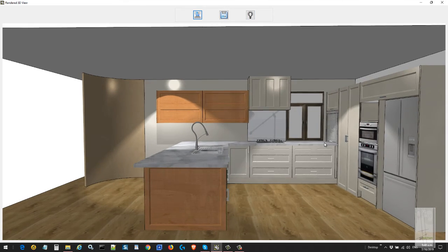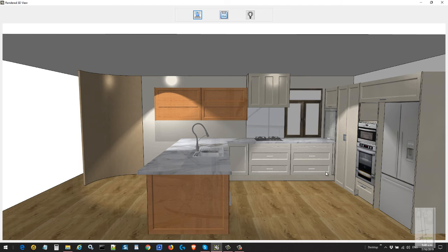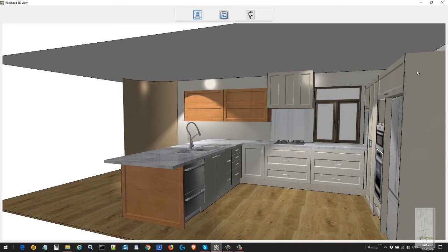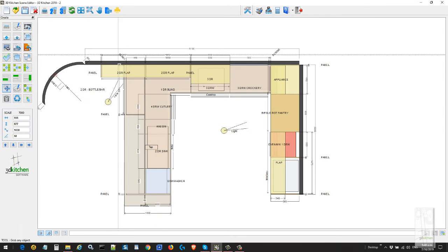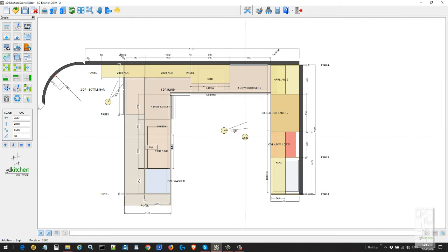Now you'll notice there's light shining on 2 different sections now. It's quite dark in this section here. If you simply want normal, just bright light, you click the plus sign, go to lights and choose directional. Click OK. Pick a position, click the left mouse button, step forward, click to place the direction you want to shine the light, and it places that into place.